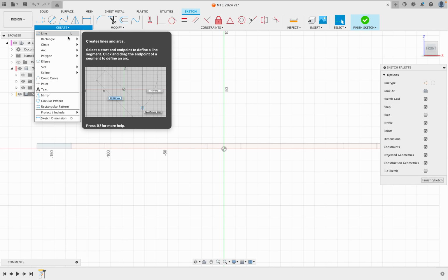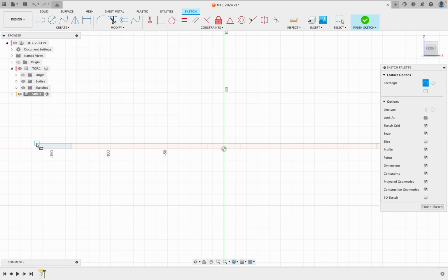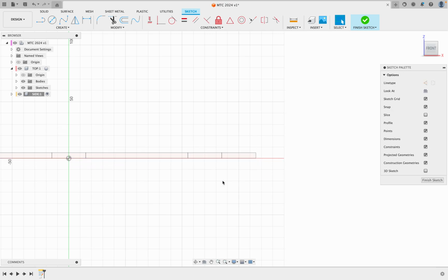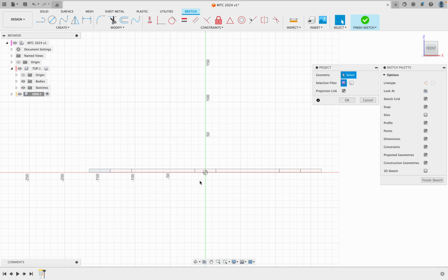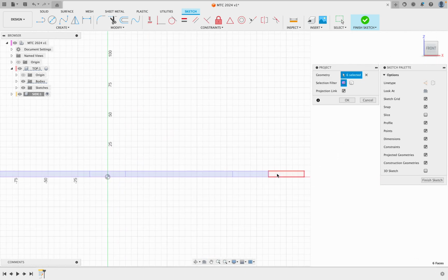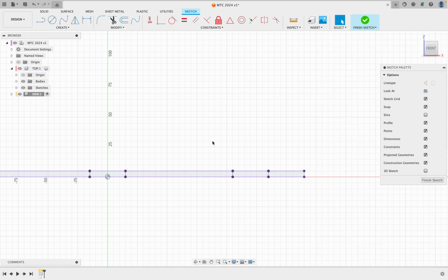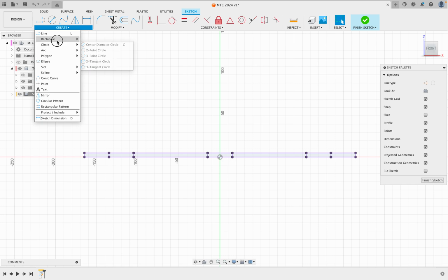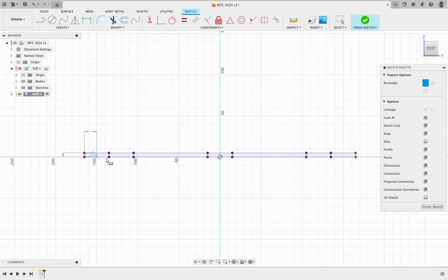And then I wanna create a rectangle. And this is a 2-point rectangle. Going from here, dragging all the way across here. Make sure it locks on that edge there. If it does not lock, I'm gonna escape. I wanna project, P for project. Boom, boom. Project onto all this stuff here. This just allows you to sketch easier on that component or on that body. Click OK.